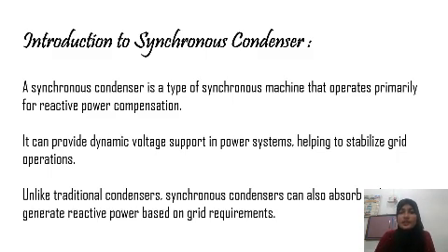A synchronous condenser is a type of synchronous machine that operates primarily for reactive power compensation. It can provide dynamic voltage support in power systems, helping to stabilize grid operations. Unlike traditional condensers, a synchronous condenser can also absorb or generate reactive power based on the grid requirements. Some key points and some key components of the synchronous condenser.